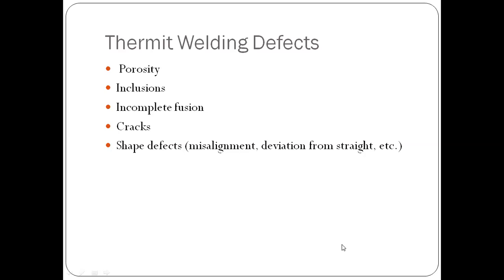Shift, so in this case some other misalignment may take place, and it may also happen that it is not properly in the shape, because the metal may have solidified for many reasons, maybe due to lack of flowability or lack of pouring temperature. These things have already been discussed, if you remember, when we covered the casting process.